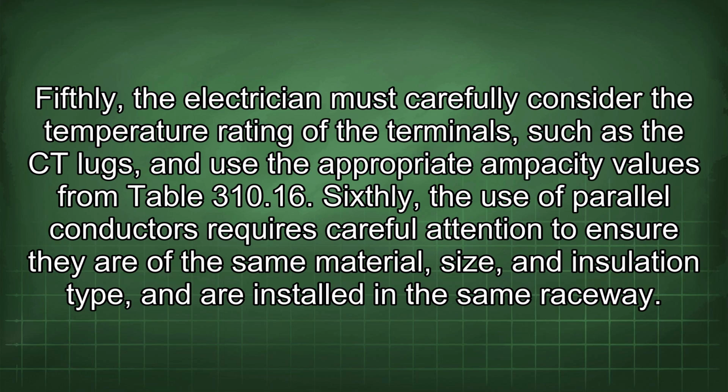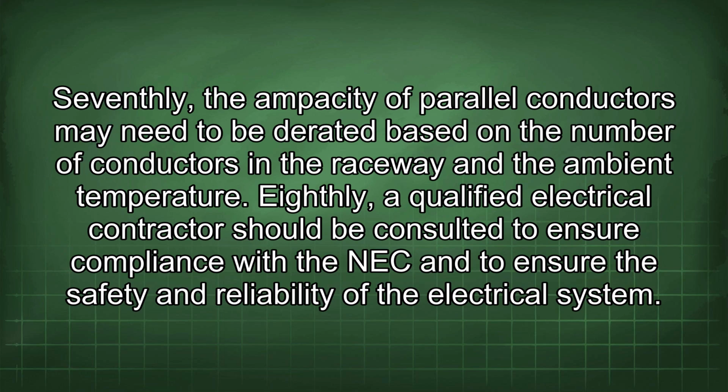Sixthly, the use of parallel conductors requires careful attention to ensure they are of the same material, size, and insulation type and are installed in the same raceway. Seventhly, the ampacity of parallel conductors may need to be rated based on the number of conductors in the raceway and the ambient temperature. Eighthly, a qualified electrical contractor should be consulted to ensure compliance with the NEC and to ensure the safety and reliability of the electrical system.